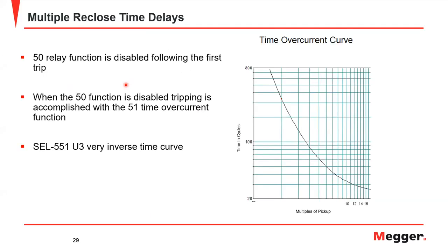So now let's look just a little bit about the overcurrent relaying. David Beard just earlier today talked a good bit about overcurrent relaying, so I'm not going to go over this too deep. I'm going to focus on how it impacts reclosing. Just a little bit about the time curve here, and this is actually the time curve of the relay that I'll be testing here shortly, and this dot is a predicted trip time for the fault current that I'll be applying.